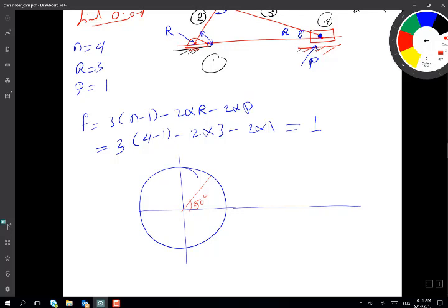With the compass, you draw link R3 from here to there, and this will find you the slider. So you have done it. You can draw the linkage at any position of the crank if this position is given. So that's one piece of information. Hence, it's a single degree of freedom linkage.